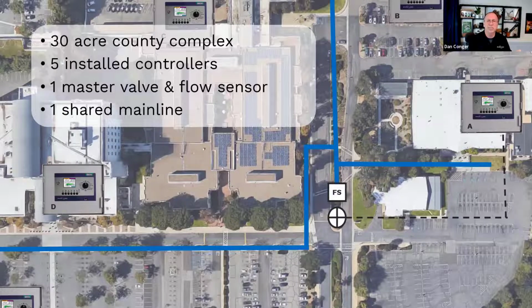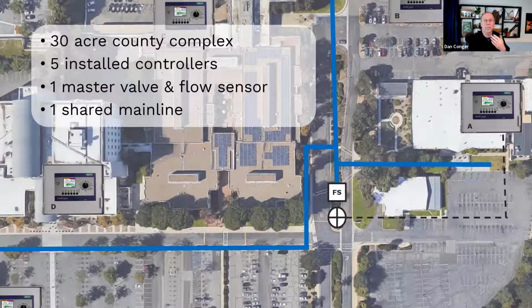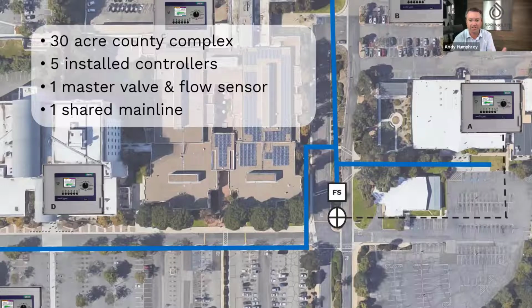So what are some challenges, right? Let's talk about the challenges that come across a situation like this without the FlowStation. Well, a lot of it depends on how big your design flow is for that main line and the scheduling, so that you don't exceed the flow capacity of that main line by operating multiple controllers at the same time. Yeah, well, not only not exceeding it, but also optimizing it, managing it correctly.